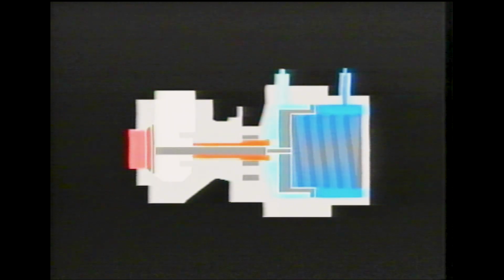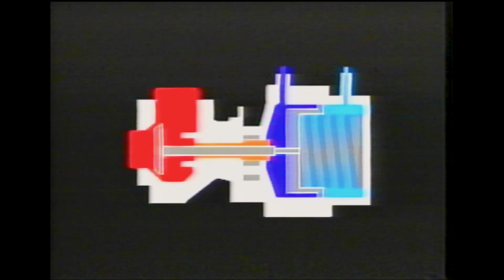0.6 bar. The function of the boost pressure operated version of the wastegate is exactly the same, but the operational characteristics differ in the following way. Firstly, the spring chamber is now open to atmospheric pressure via a short piece of hose. Secondly, the only operational chamber is the one on the valve side of the diaphragm, which is now operated by boost pressure.